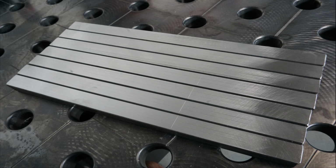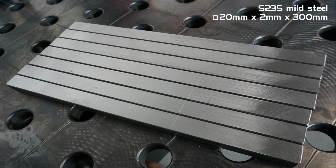The following experiments were a little tricky for me to come up with. They look simple, I know, but quite some thought was necessary to keep things comparable. What we'll do is we will lay down one weld bead of given size on each of these samples of square tubing. On each sample we will employ a different welding strategy and then compare the resulting distortions. To ensure comparability, the following procedure is complied with. The tube's weld seams are all kept at the side.